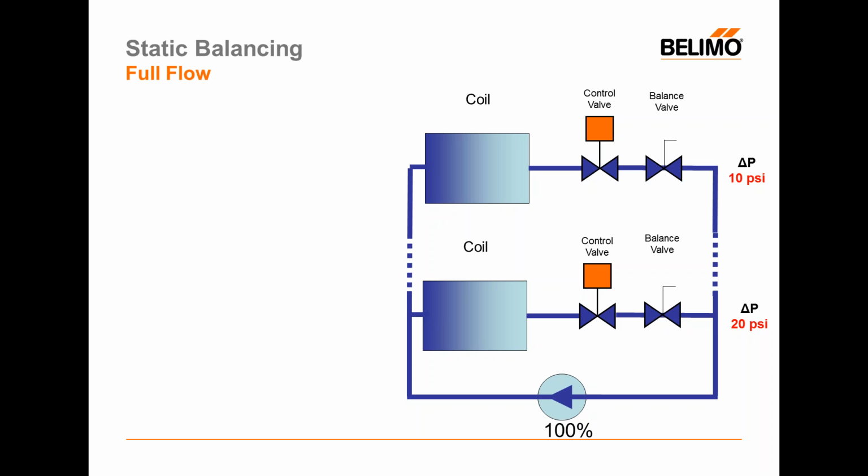The first floor of that building is represented by the first air handler coil, control valve and balancing valve that you see, and then there are some dotted lines, which would be the rest of the building, and on the very top floor we would see our second coil, valve and balancing valve. So we're looking at the first floor and the 10th floor of our building, and we're going to juxtapose those because they're going to have vastly different behaviors, even though in this case we're going to assume all the coils are identical, the control valves are identical, and the balancing devices are identical.